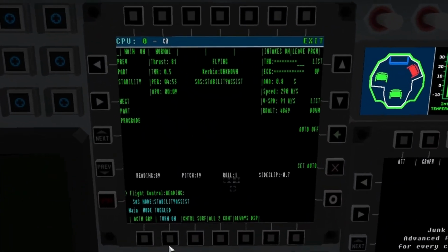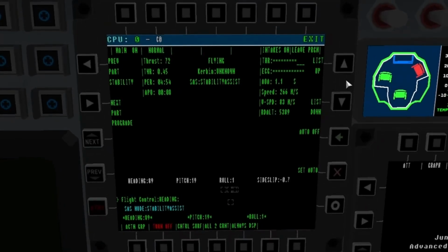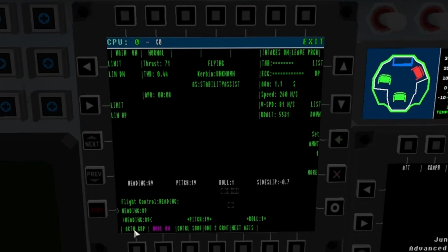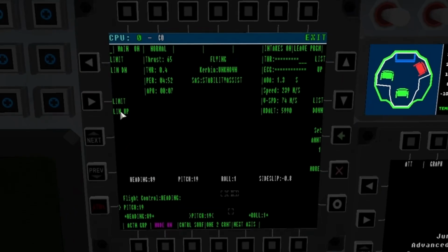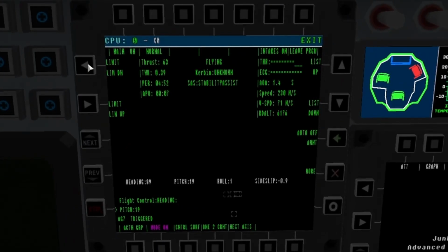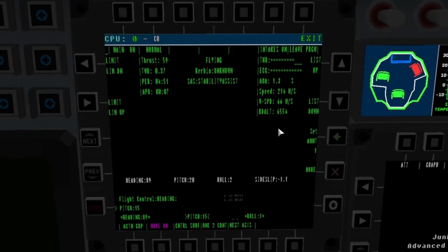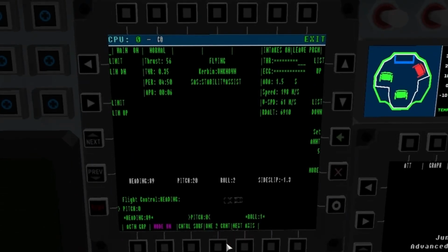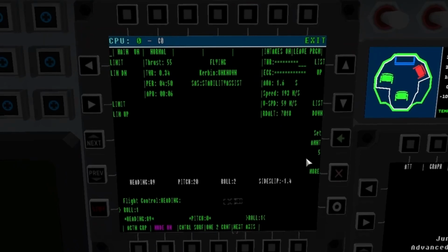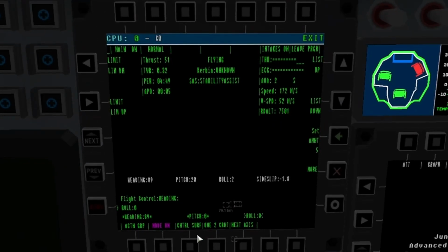Now we'll look at this. This right here is a rudimentary autopilot. We're going to set everything to current. Go down here. Heading 89, pitch. Alright, so right here is where we go to the next axis here. And this is the amount we adjust by. 16, 15, we're going to adjust by 5. I want the pitch to be 0. Next axis. You can also, actually, if you press 1 to current, it will give you the option 1 to 0, you can zero it out.